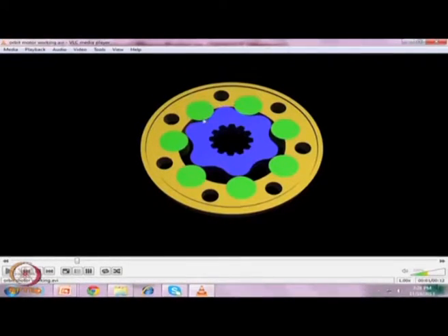Now, the other part of the envelope is the circle on which these rollers are kept, I mean on the outer body. This is slightly less than the circle which is called the pitch circle, slightly less than that, so this roller does not come out, and it is selected on the basis of the topmost position of this roller. At this position we can say the piston is at its top dead center.